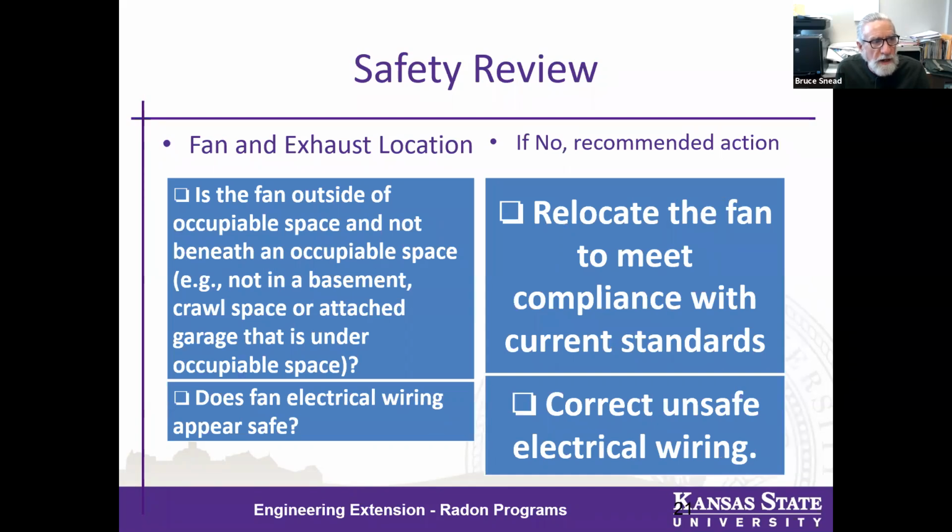Where is the fan and where is the exhaust location? A key issue in radon mitigation system installation, sometimes a point of dispute, is the fan outside occupiable space, not beneath an occupiable space? And does it have proper fan wiring? If it's not properly located, the recommendation would be to relocate it to comply with current standards. And if the wiring is unsafe, then correct that.